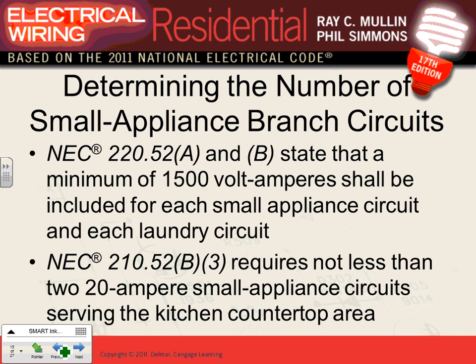We'll talk about this. This is what the code refers to as small appliances branch circuits, guys. When we do the load calculation for the whole apartment building, they allocate 1500 volt-amps for every circuit. Two of them will be 3000. That's based on the code.